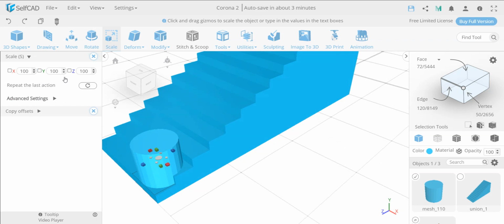And in scale, I can scale. Actually, I need to scale only in 2 directions. So I need to scale the Y, the height is okay. Actually, it'll make it even bigger. So let's say I want to have this 25 the size. So I can scale this to 25. And I'm sorry, this is something very important to know. Size is doubled in radius. So if I make 25, if you are in the tool, you would use 12.5 radius, because the radius is just half the size. So this 25 is like a half a radius in this case.